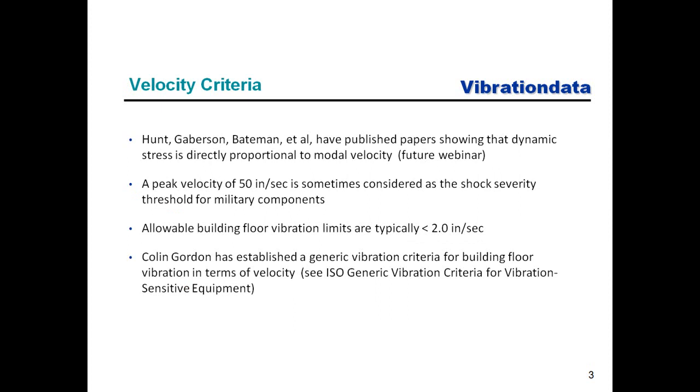So we measure acceleration, but sometimes we want to know what the corresponding velocity and displacement are. And here's just an example. There's been a series of authors and researchers, for example, Hunt, Gaberson, and Bateman, who have published papers showing that dynamic stress is directly proportional to modal velocity. And we'll cover that in a future webinar.